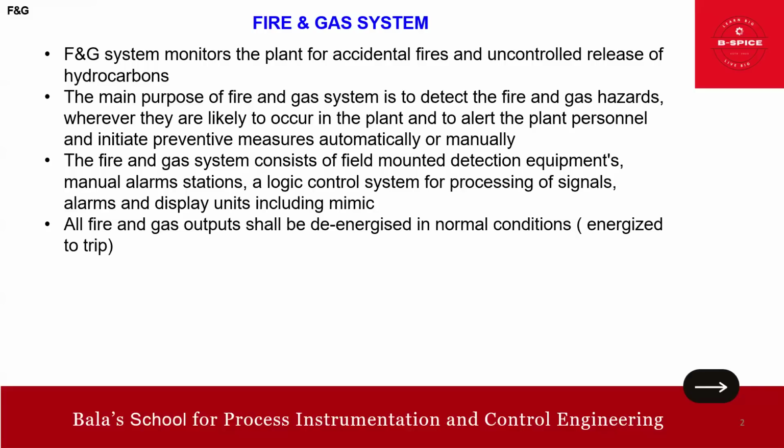So all fire and gas output shall be de-energized in normal condition. That is the point, friends. All fire and gas output shall be de-energized in normal condition. Energized to trip. Normally it will be de-energized in normal condition and energized to trip. Just remember.